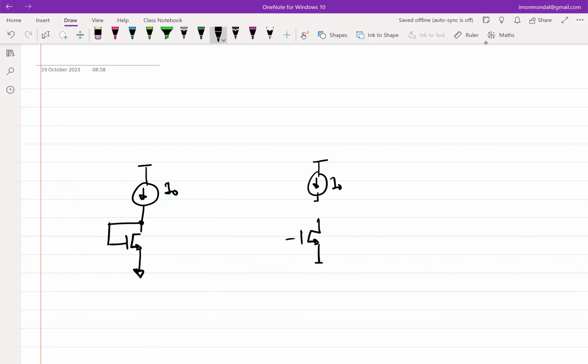I have a current source I0 and I have this transistor M1. We wanted to ensure that the drain to source current of the transistor becomes exactly equal to that of a current source. And the motivation for that was to ensure that the GM of the transistor does not change. Right, so that was the whole motivation. We don't want the GM to change with respect to threshold voltage. So that was the reason we would have liked to do this.